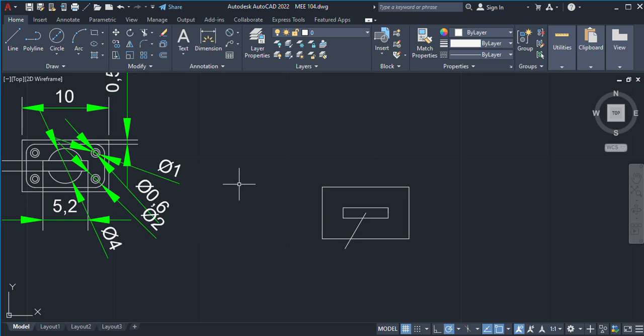Exit. Now go to circle, center diameter. Tap on the center like this. Our diameter is 4. Just press 4, enter. You see it like that. We don't need this again, it was just to get our center, that's all. So you delete it. Now we don't need the middle one. You go to trim, this trim here. Trim this off, trim this off.